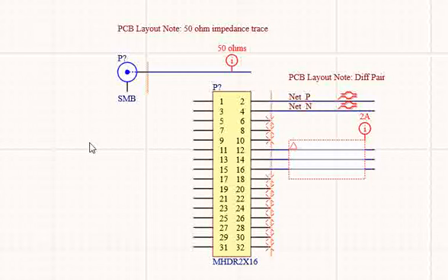In OrCAD, you will have another symbol, or in another tool, you'll have another symbol. So this indicates that these will not be covered by the ERC when we run it in the tool, and the tool ignores it. And also, we as schematic readers understand that, yeah, these are intentionally unconnected. These are actually not used in the design. So this is one way of mentioning it, right?